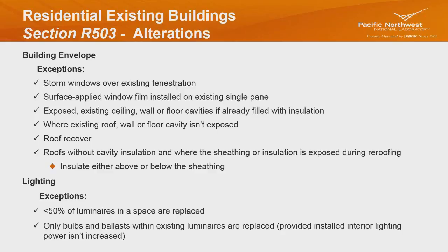Where the existing roof, wall, or floor cavity isn't exposed, so if I'm just doing a roof replacement on the top membrane of the roof, maybe just the shingles, and I don't go down to expose the insulation, I'm exempt from having to meet the energy provisions for putting more insulation in that ceiling. So roof recovery is another one. And then there's another one for roof provisions as well that depends on whether you're exposing the sheathing or not.